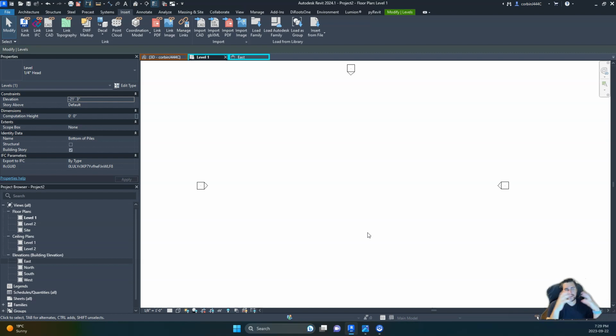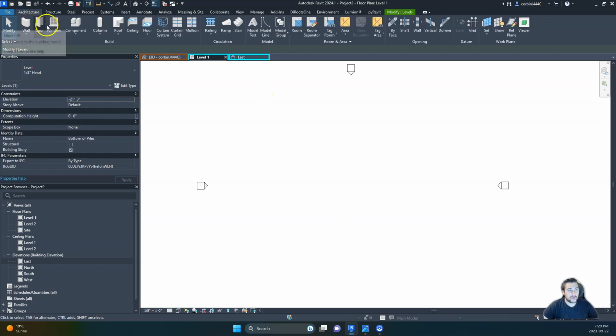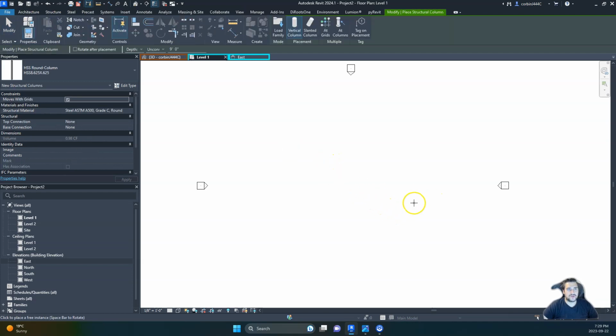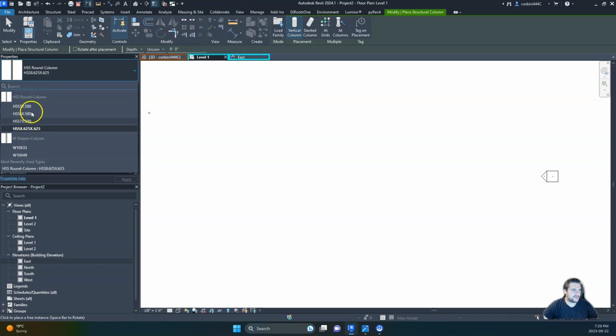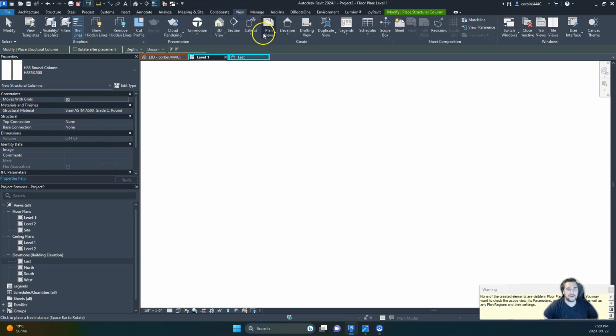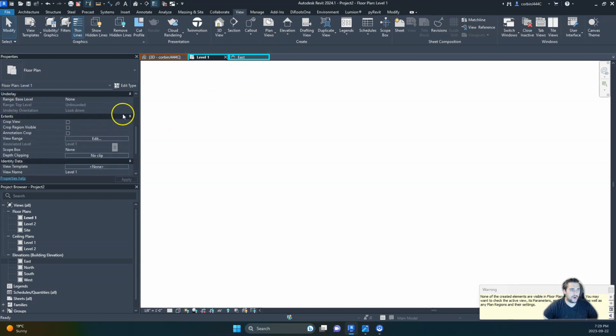Depending on the depth of the dock structure, where we have like 20 feet depth, they'll probably stick around a 5 or 6 inch column. If we have 100 feet deep, which is quite possible in the water in various locations, we want to potentially increase the diameter. So I'll start with just our 5 by 1/2 columns. I'm going to place one here and show you what's going to happen. You're not going to see anything, and there's a few different ways to fix this. Probably the best way from a drawing perspective is to turn on underlay. We want to turn it off after.